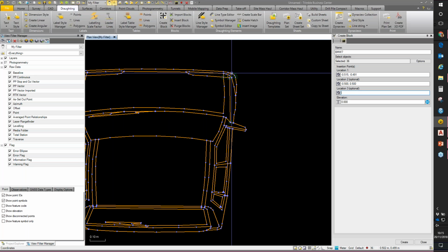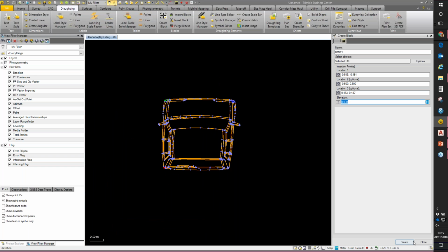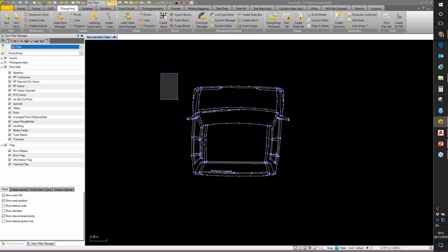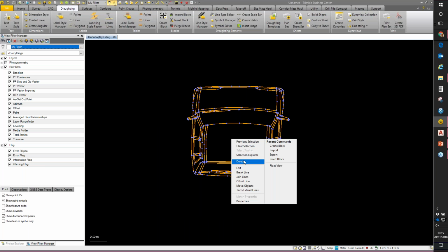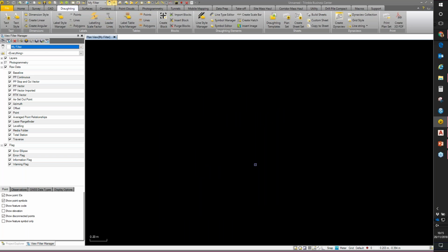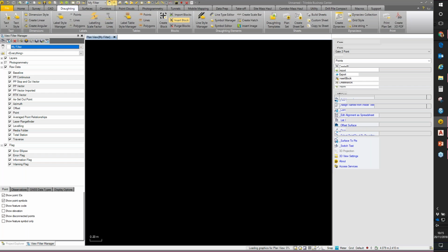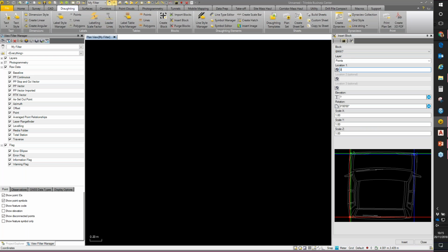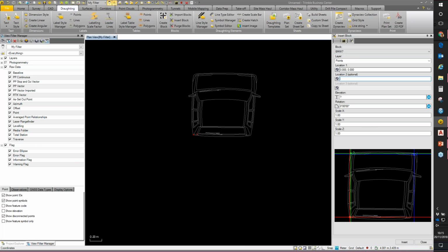So in this corner over here, that's my 3 positions specified, and go to create. Yep, let's confirm it's been created. I can close that tool, and now I can take that out of the drawing and place it in as a block. There we go. So again, let's just put in some coordinates to place it on here.